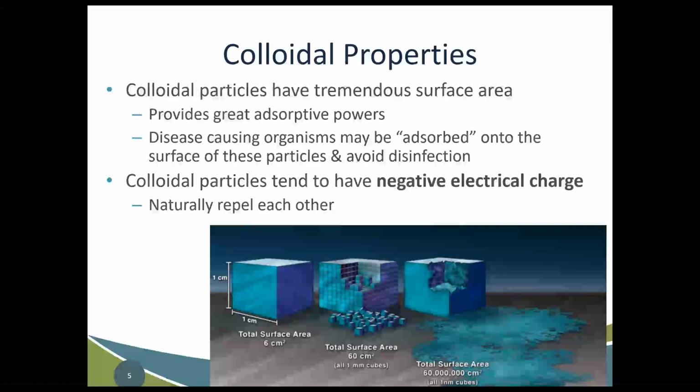It's important to always keep in mind throughout the presentation that it is a multi-barrier approach, but each barrier relies to some extent on the previous barrier. So you've probably heard people say you can't disinfect something until it's clean. Well, that's because we need to remove these little particles where the disease-causing organisms might be bound up and able to avoid our disinfectant.